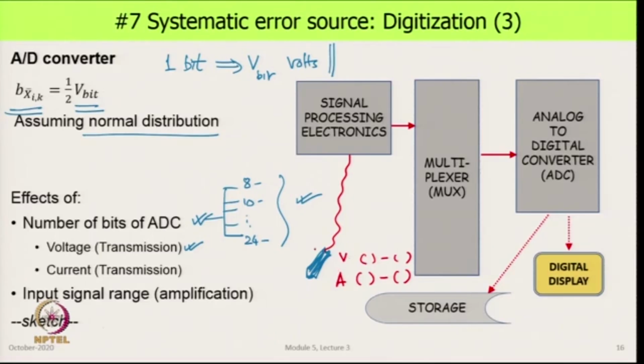If this puts out a certain value of the voltage, by the time it gets here, because of line drop, the voltage here will be slightly lower than the voltage here, and you have introduced an error, a transmission error. If these were small distances, we could live with it, that error is not very significant. But for long distances, this is not an option.